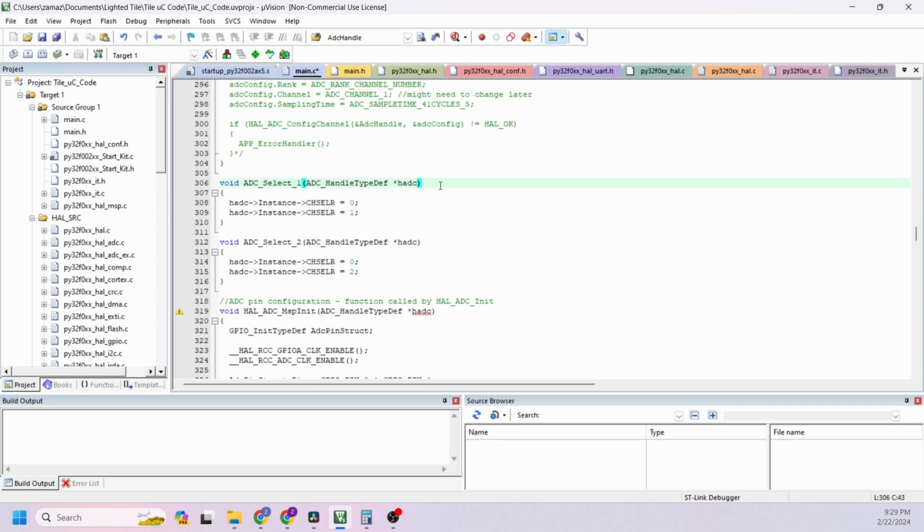for each microphone, 2,000 times a second. I then take the readings. I see if the reading is greater than or less than the previous largest and smallest values, respectively. If they are, I save it as the new greatest or lowest value, and then I recompute the amplitude by taking the difference of the two.